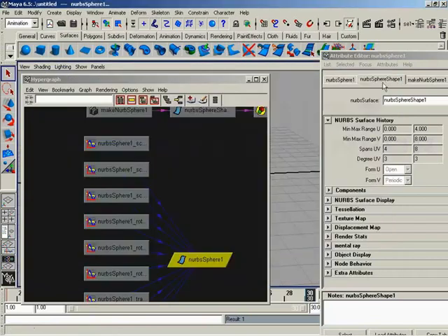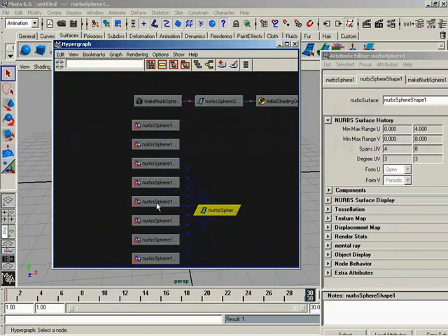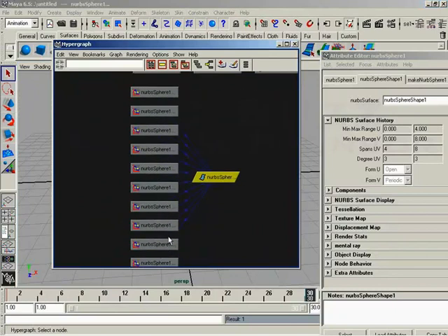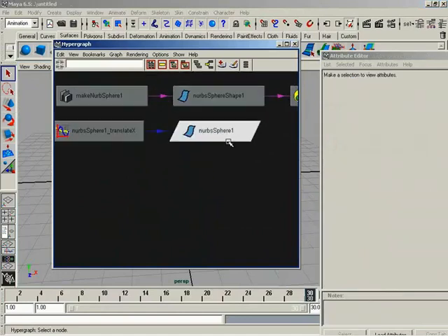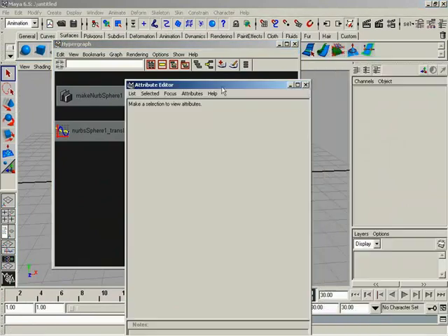Now you really will have a giant file size that's just storing a bunch of data that's useless. So what do we need to do? Well, first of all, in here, I could simply delete everything. So let's see. Translate X is right there. So I'm going to grab all of these, hit delete. Ooh, that cleaned things up. I'm going to grab visibility, hit delete. So look at that. I'm now left with only one animation curve feeding into my NURB Sphere 1 transform node.